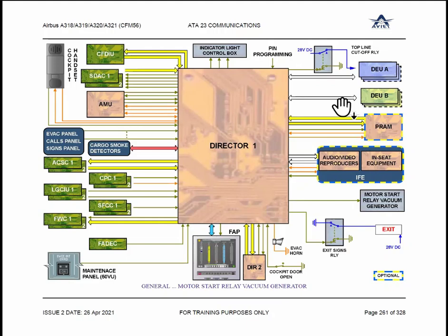Sir, CPC is there in enhanced version for pressure. I focused on it in the previous interfaces. We were having the switch. Here, direct CPC is giving the pressure value. Correct. That is what I explained, that engine running is coming from the FADEC and decompression signal is coming from the CPC. LGCIU, SFCC, FWC remain same. STEC, CFDIU remain same. Yes, sir.